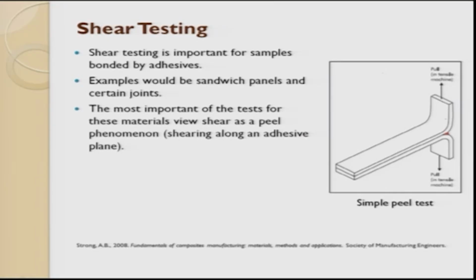Preparing a test sample is also a very challenging job, and this cannot be done after a full product is made. I cannot make the product and then peel it. This has to be taken care of right in the beginning itself. While you fabricate a component, make sure that you are fabricating it for this shear test.